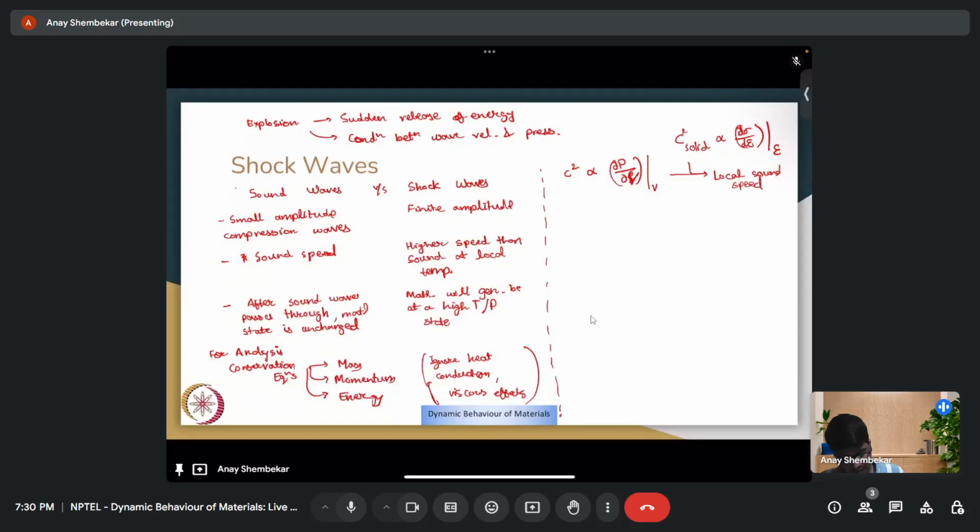So now coming back to the important condition. The condition is as pressure increases, your sound wave velocity or wave velocity, I'll write it as u, should also increase. This is the important part. If you think about it in another manner, if with increasing pressure there is a decrease in velocity, then as the compression moves forward, the higher pressure components will slow down, and those different components will move at different speeds.